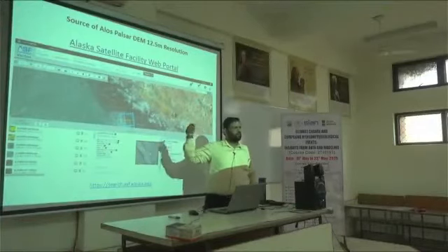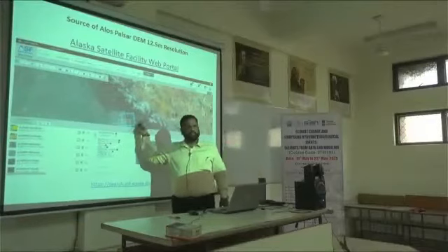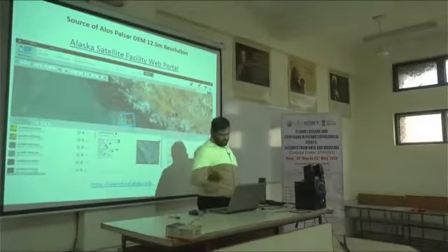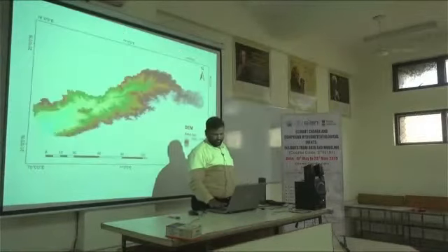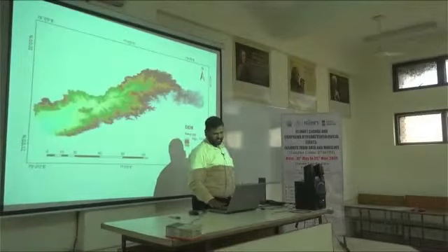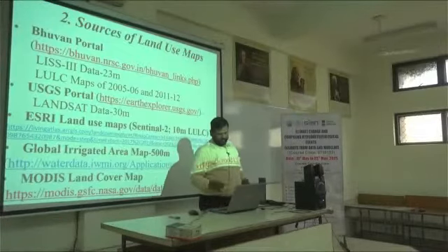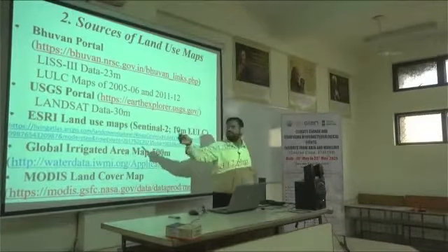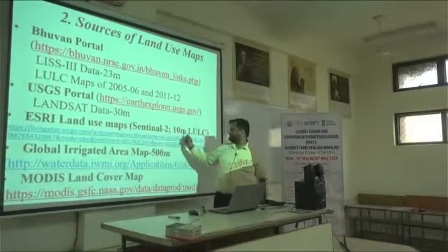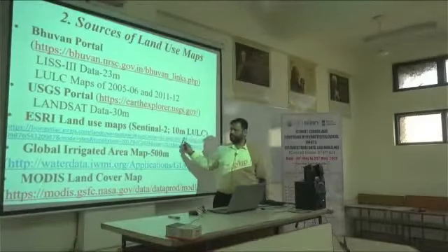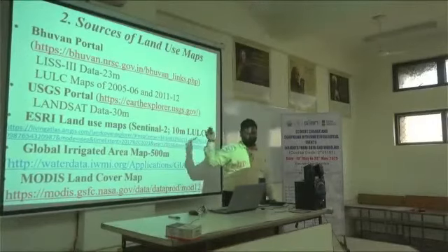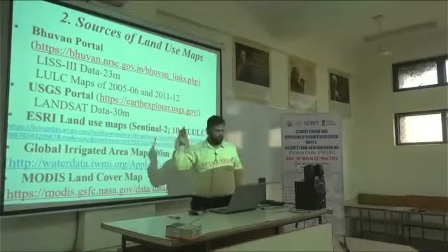If you want some kind of fine resolution data, you can go for Sentinel data that is available at 10 meters, from the Alaska Satellite web portals. So these types of inputs we have already discussed. Then if you don't want to create your own land use map, then ESRI has provided Sentinel-2 data at 10 meter. They have directly given you the land use, land cover maps for the entire world.